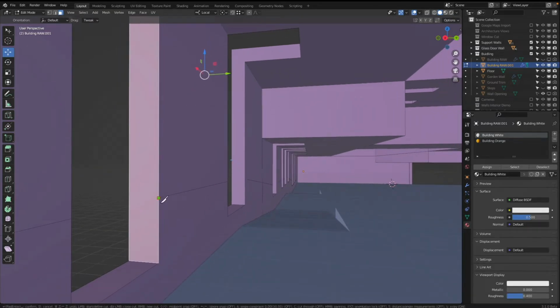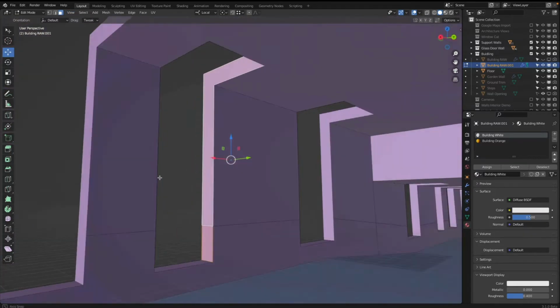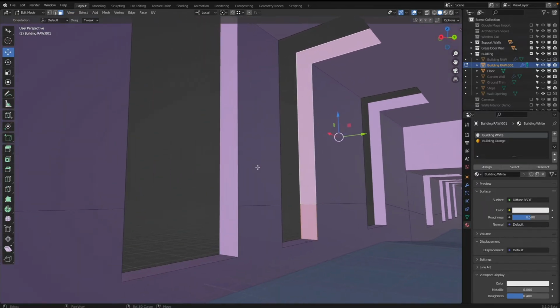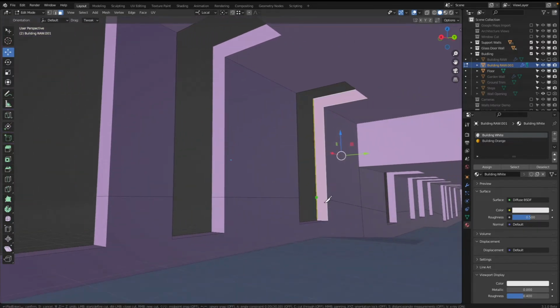So let's say here with the knife tool there, I select, then Y, this is the Y direction, click OK. Let's frame this and rotate the view. Okay, I did not slice anything else. So I select this face, K, Y, click and enter. And maybe here we do 1, 2, click Y and enter.